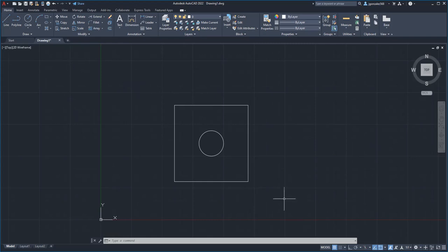Okay, so the point at the beginning of chapter 6 is basically to get more comfortable with the snap setting, because they're very helpful. I'm sure you're starting to see that if you haven't used them already. So select the line command. Now notice how my endpoint snap is on, my midpoint snap is on. See how they're being highlighted? So what I want you to do, let's start down here actually, the lower left. Click here, and then connect the line to a tangent point to the circle.